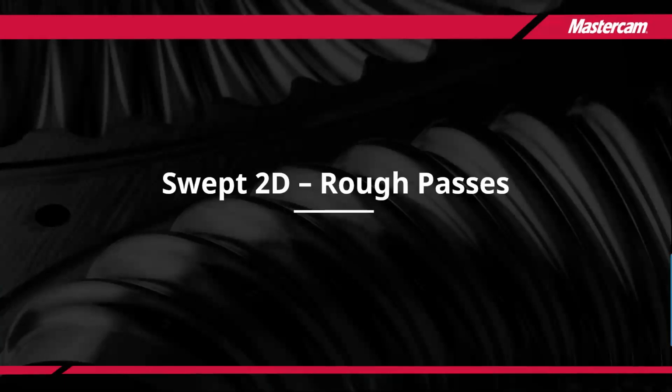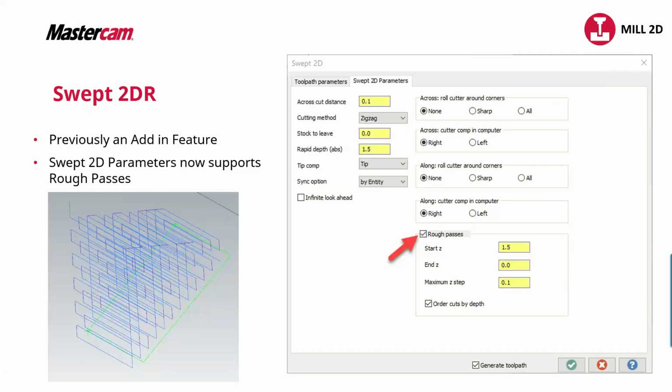We're going to take a look at Swept 2D. If you are familiar with Swept 2D as a 2D finishing toolpath, you may or may not be aware of an add-in called Swept 2DR. Swept 2DR was an add-in in previous versions of Mastercam that enabled Swept 2D to use roughing passes. In 2024, that add-in has been removed and rough passes has been built into Swept 2D.